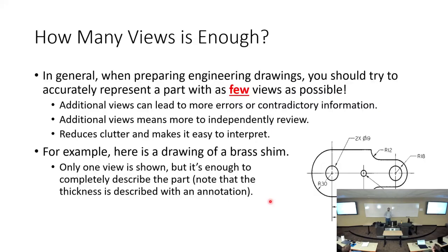Here's what I'm going to do. I'm going to say we need this dimension right here. Let's call it 3 inches. Do I need this dimension? No. Why? You can do 8 minus 3, 5. It's not independent, right? Remember in math when you learned about independent variables versus dependent variables? That's sort of what's going on here. This 5 is a dependent variable.